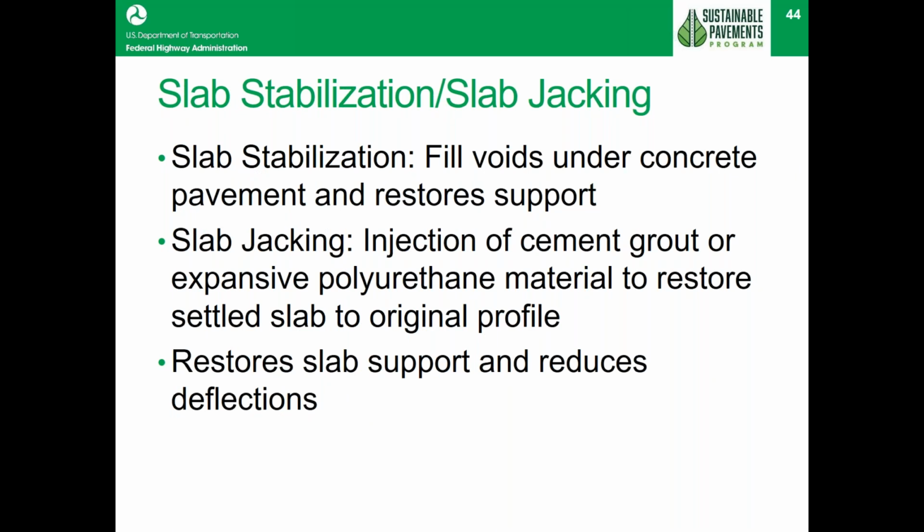Now, this is a little bit of a maintenance activity, I guess, and this is one way that agencies can deal with sunken slabs or some slabs that have become unstable on the highway. The process really amounts to drilling holes through the slab and then injecting some material to either raise the slab or stabilize it. And you can kind of see some of the materials on the screen here that we use with it.